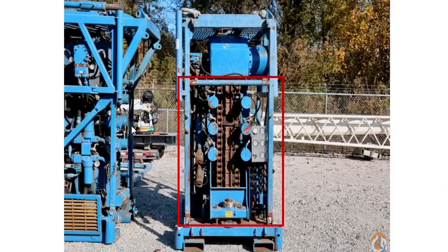So here an injector is shown for explanation purposes. We can see the chain assembly over here, and these are the gripper blocks attached to the chain assembly, and this chain is being driven by these two hydraulic motors. A similar chain is also installed on the opposite side. So typically one injector has two chain assemblies rotating in opposite directions through a sprocket and ultimately the hydraulic motor.